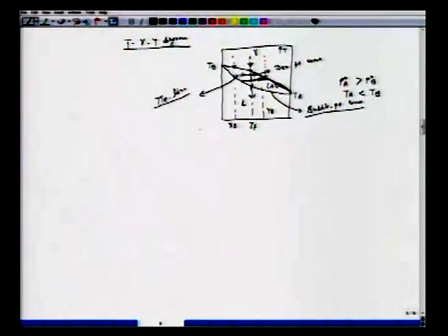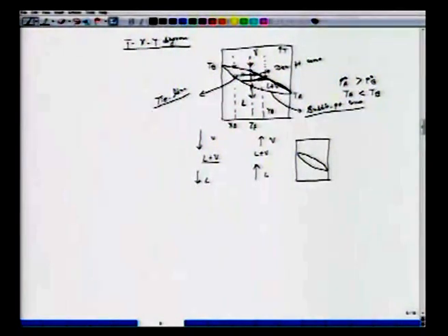The idea is that either we start from the pure vapor to reach the zone of pure liquid through this L plus V by condensation, or we start like in the previous class with the pure liquid and heat it till we reach L plus V, and then we have this pure vapor. Both of them will trace the same TXY diagram in a general curve like this. So either you go from here or you start from here, it will give the same results.